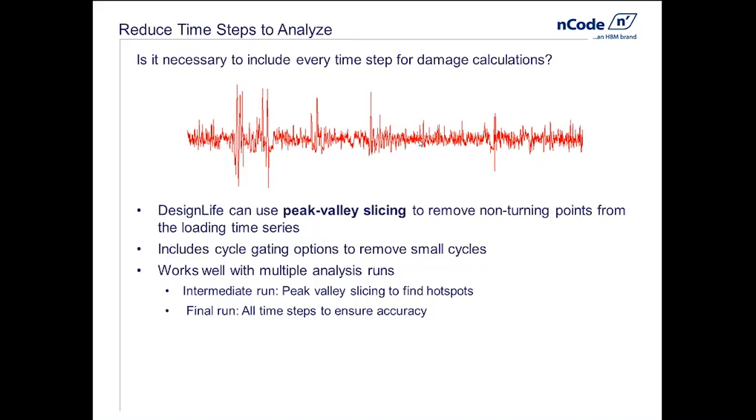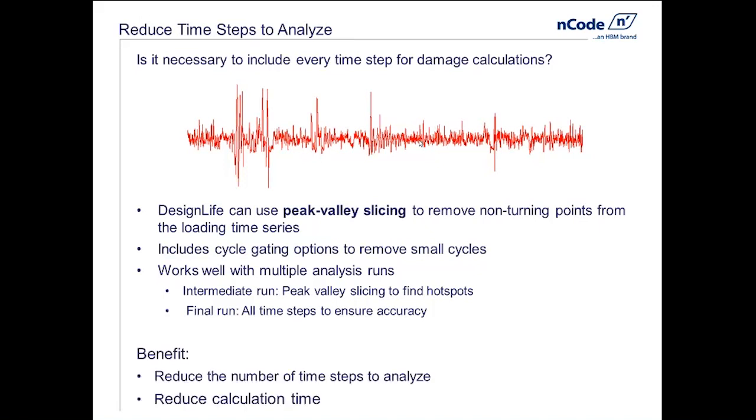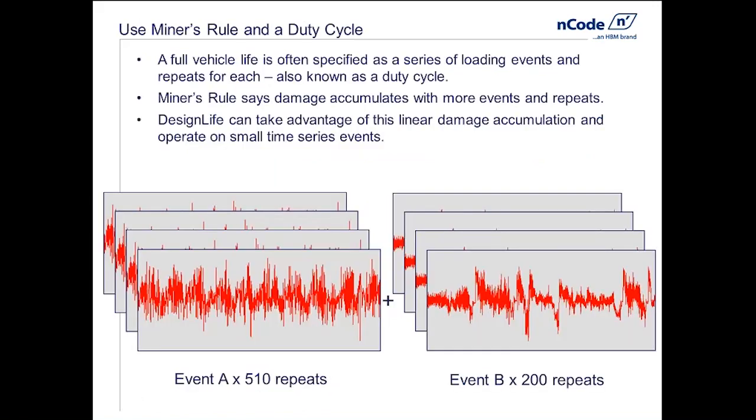So these two things work together very well, multiple runs and peak valley slicing. The benefit of doing this is that we're reducing the number of time steps to analyze, and ultimately then we're reducing calculation time, and that's the whole goal of what we're talking about today. So let's move on here.